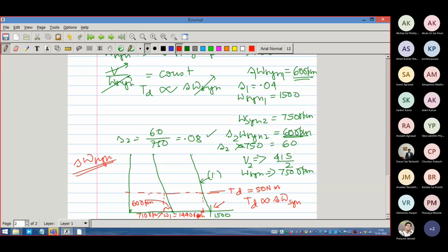Here it is a function of slip speed, when you have the ability to change the synchronous speed and, while changing it, are clever enough to change the supply voltage as well. With this combination, the machine's torque is proportional to slip speed. That is the core philosophy of operation of the machine.